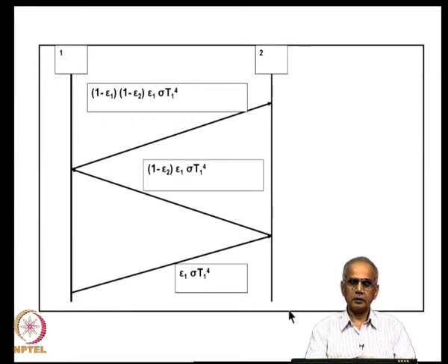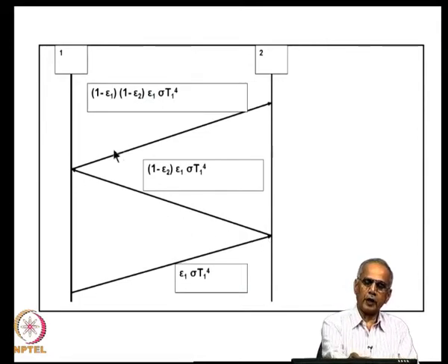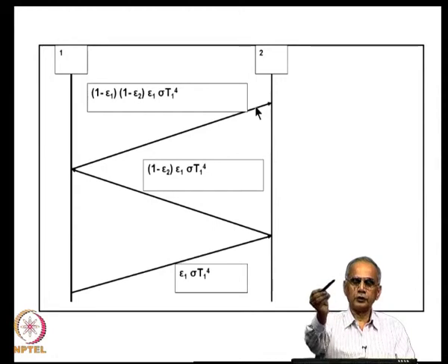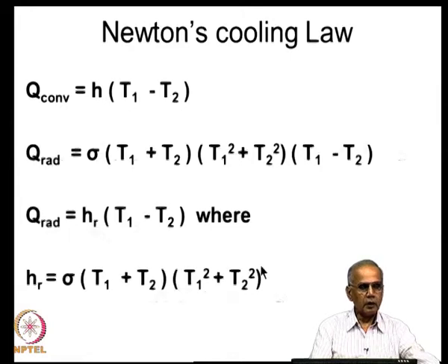Now, the simplest way to understand the heat transfer between the two surfaces is to do simple ray tracing. The radiation emitted by surface 1 reaches surface 2, is partly absorbed, the remaining part is reflected, and it is reflected back to surface 1 again. So, one can add up the total number of photons arriving from 1 to 2 and being absorbed at 2 as an infinite series, the direct contribution, after 2 reflections, 4 reflections, 6 reflections, and so on. This is the standard ray tracing technique.